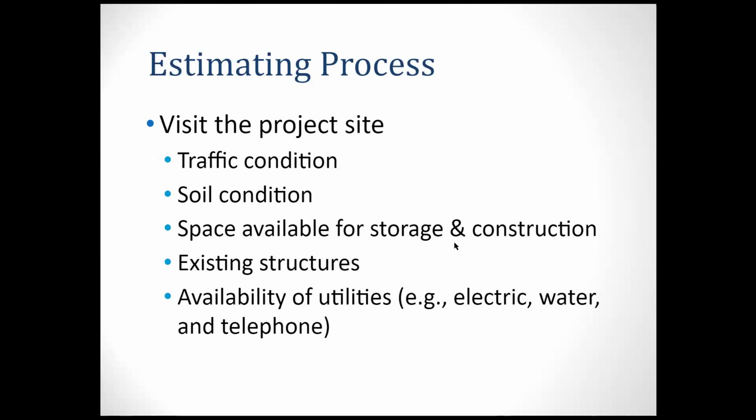Also the traffic condition is very important. If we're working in an urban area, in downtown areas, the traffic condition actually impacts your material supply deliveries, right? It impacts your schedule, right? So consider the space available for storage and construction. If you're doing ABC or another competition, then you may need to have a site plan. In that case, you will think about what is the entrance, what is your exit, right? And where are your storage locations. You may not be able to provide on-site storage. Then in that case you need to look around the surroundings. Where is your outside storage, right?